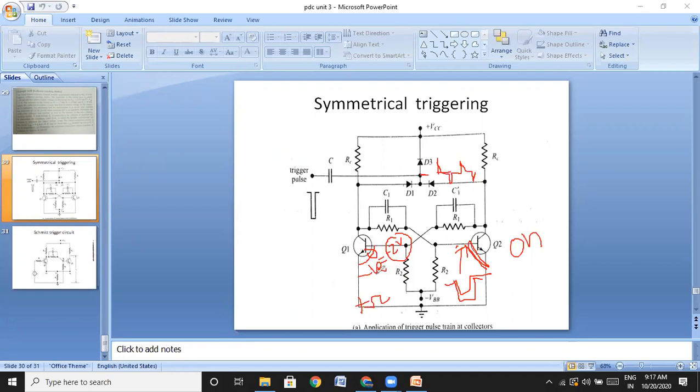It should be greater than 2.6. When you apply around 3 volts positive pulse, the off state transistor will move to the on state. This requires a large positive pulse, with a magnitude of around 3 volts. When you apply 3 volts, it will move to the on state. I am taking these values as assumptions.